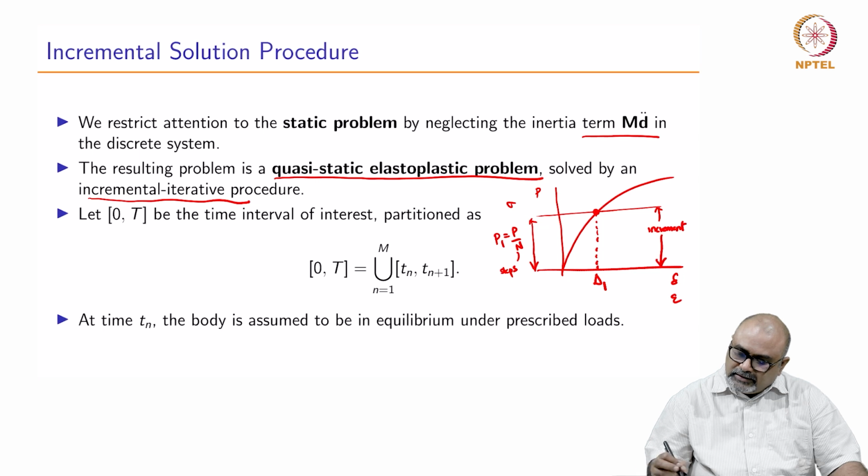Following an iterative procedure starting with an initial stiffness and reaching this equilibrium, we can then iterate on the solution, and this iteration is followed in a manner where the stiffness is going to depend upon what is the state of the loading that we have, or the stiffness can be a constant. So, the stiffness is going to depend upon what is the extent of deformation.